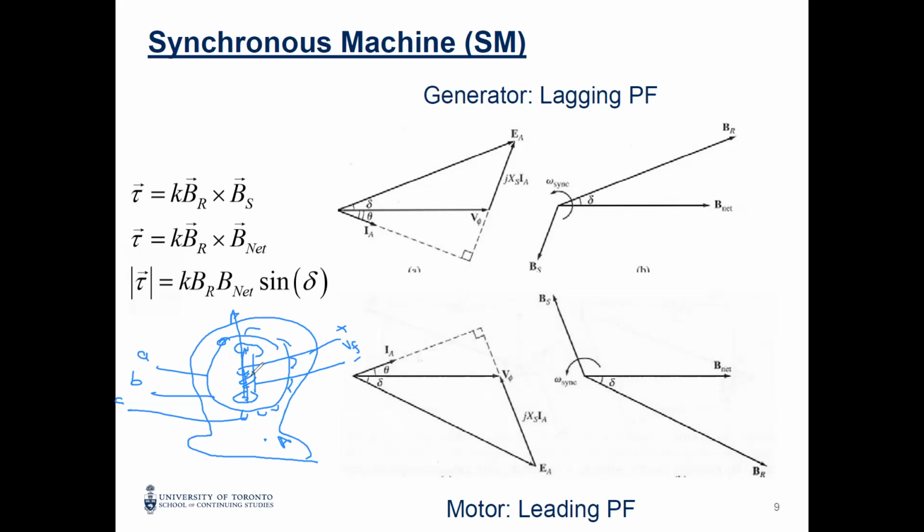One reason for this is that, as I said, synchronous machines are used for very large ratings, and the windings for the three phases here are large. So you cannot put them in the rotor and rotate them. They are heavy, large, very big conductors. To rotate them, similar to what we did for the DC, it's impossible. If you remember for the DC, we had the stator, and for the stator, we had the field.